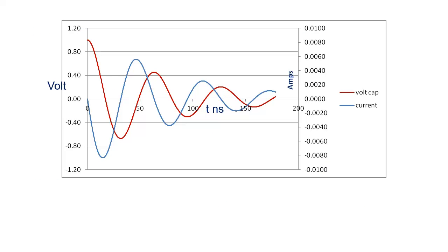Let us plot the capacitor voltage, in red, overlaid on the current, in blue, once more, but over a longer time duration. We observe that a maximum magnitude in current corresponds to 0 capacitor voltage. And, a maximum magnitude in capacitor voltage corresponds to 0 current. This is the so-called quadrature relationship between the two.